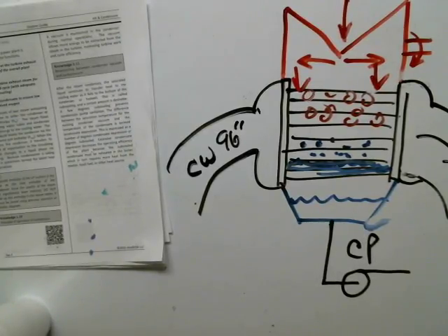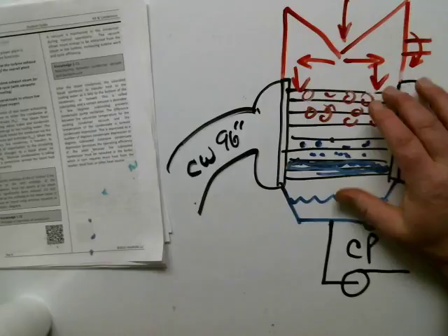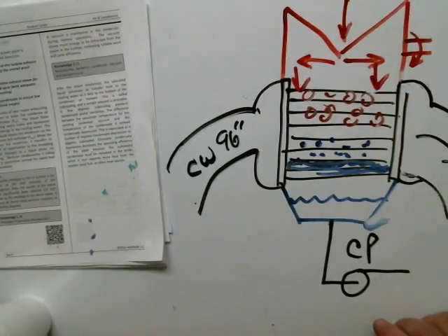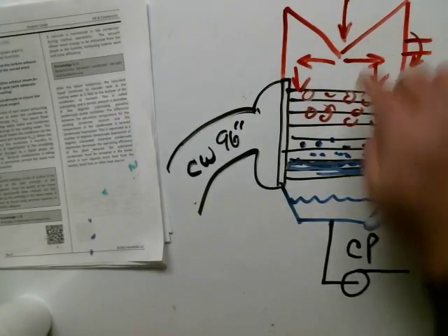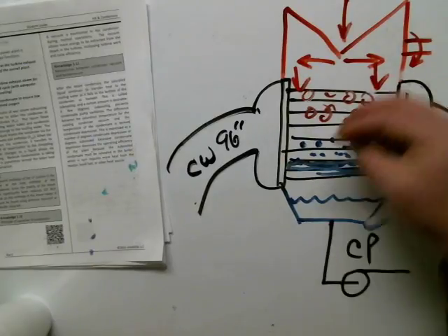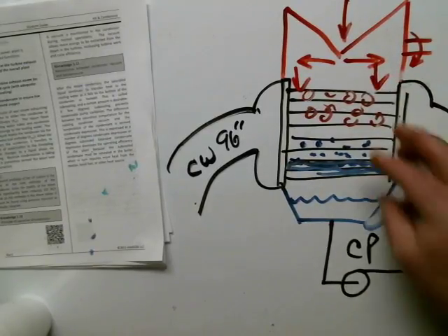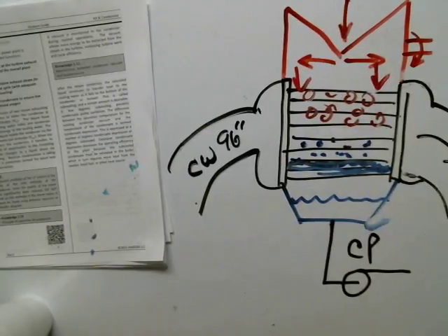So the condenser is a really useful tool in our steam cycle, a component rather. It serves a lot. Keeping it under a vacuum is going to allow us to extract more work out of this turbine. It's going to allow de-aeration of that condensate as air and non-condensable gases come out of solution.